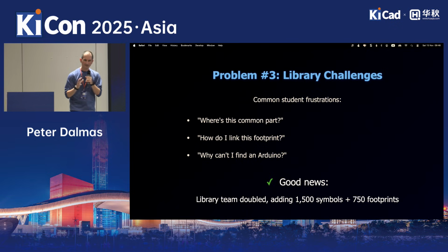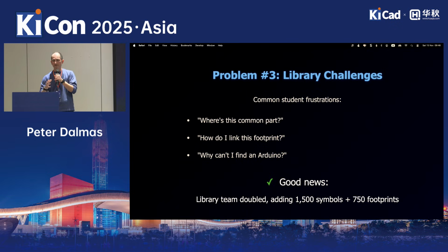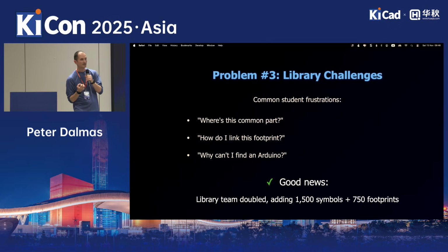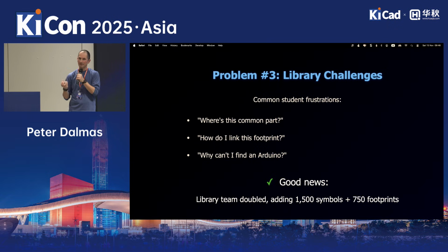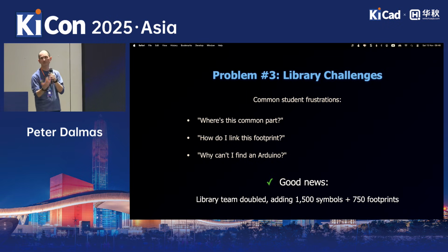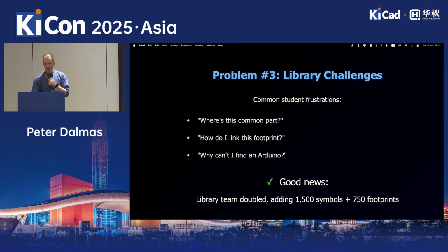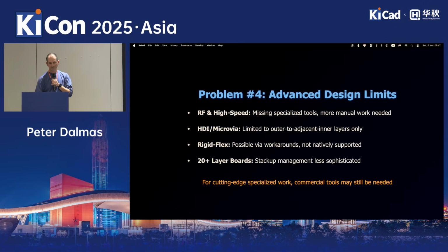Have a centralized database so we know that the parts that we are using in our project are the latest version. And with a centralized database, when we share the project with other people, we know that they are getting the same version, symbols and footprints as the ones in our project, without having to share perhaps outdated copies in the project file, which could be old. You see the problem. It's just a couple of examples.